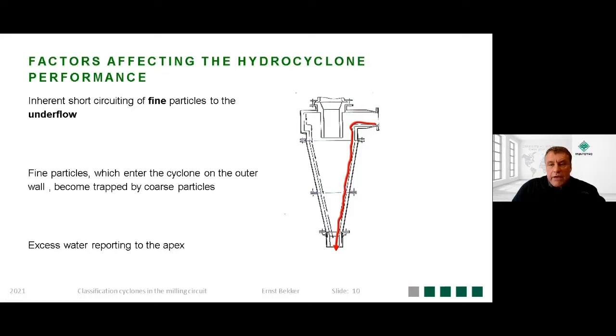Viscosity starts to become a factor to keep in mind. Then we also have a mechanism where the particle sits at the side of the hydrocyclone. There's two forces, a drag force and a centrifugal force. But if the particle sits on the side of the cyclone against the wall, there's no water behind it, so the drag mechanism is not applicable. So the particles can actually not get into motion.